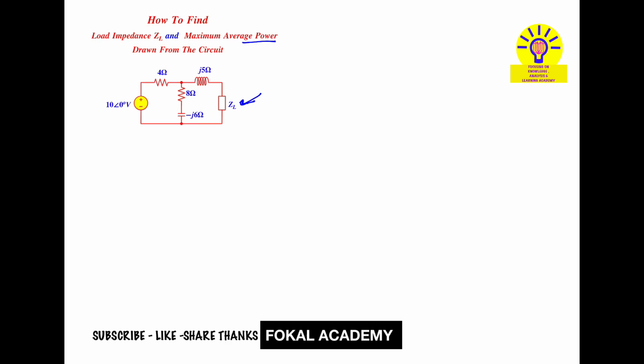So here we need two calculations. One is Thevenin's voltage and Thevenin's resistance. But here the circuit has reactive components, that is, an inductor and a capacitor. So the first step is Thevenin's impedance, and from that we will get the load impedance and Thevenin's resistance. Now first of all I am going to find VTH.